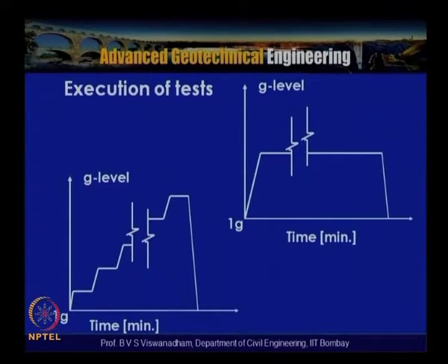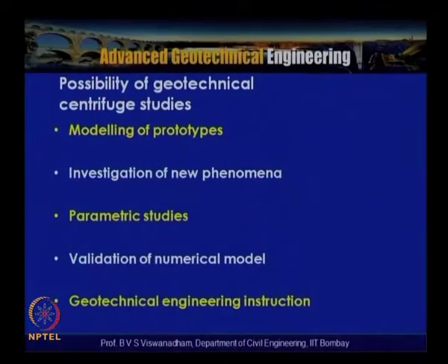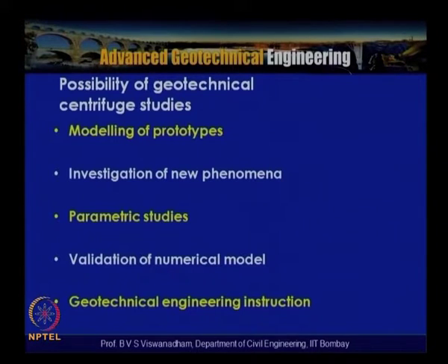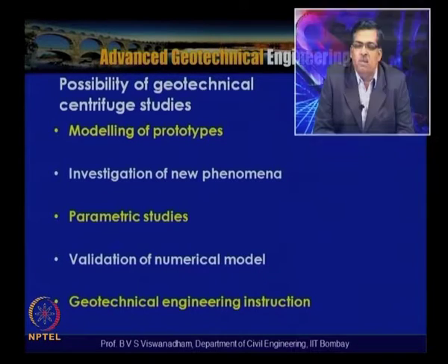But nowadays, with the development of different actuator systems and rainfall triggering events or earthquake triggering events, the constant gravity tests are adopted widely. So the possibilities of geotechnical centrifuge studies include, we can model a prototype. If you are interested in understanding whether a particular prototype structure which has been constructed is safe or not, or what its performance will be after 5 years or 10 years of its life, it can be studied by using this centrifuge based physical modeling technique.